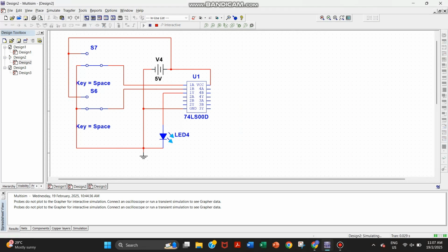So this is the NAND gate, which does the exact opposite of an AND gate. Currently the switch is 0 0, and the output is 1. When you switch it to 1 0, the output is still 1, and when you switch it to 0 1, the output is still 1. When both are 1, it will become 0 instead.